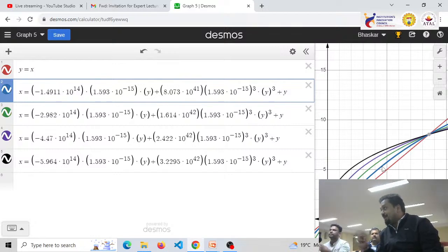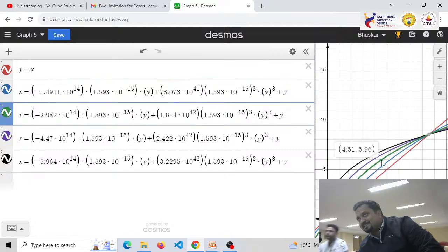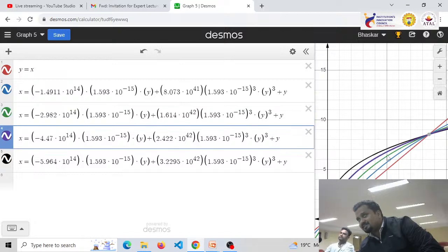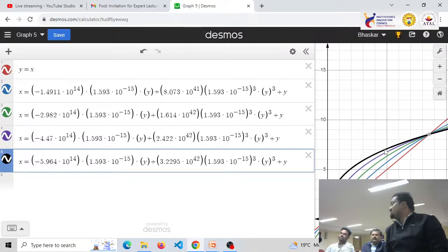I am applying a lower supply voltage and the voltage drop across the dielectric is higher. And the same thing is observed in every graph, every characteristic, like here, 7.07. So what we can conclude from here is that the negative capacitance state in the ferroelectric is highly unstable.